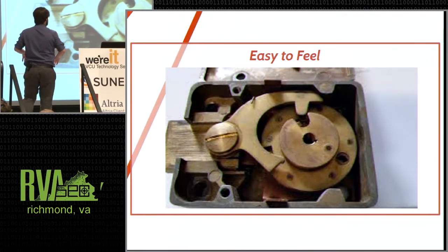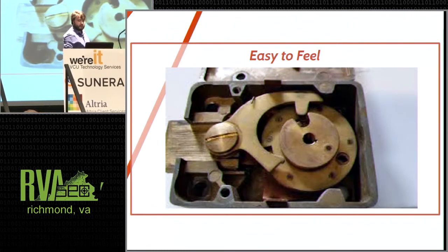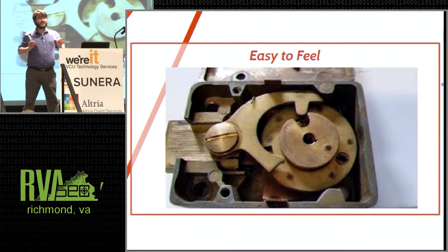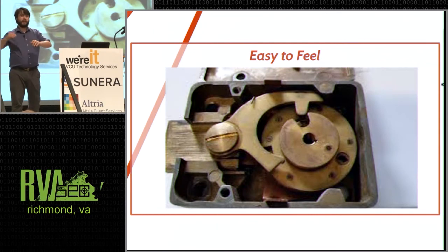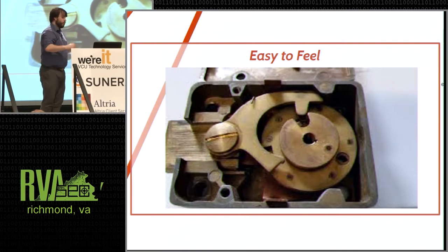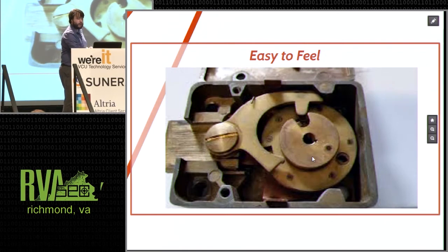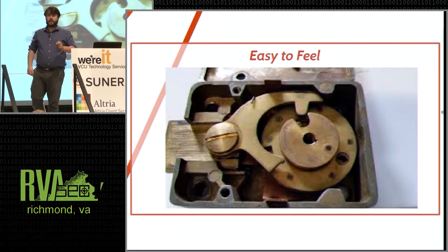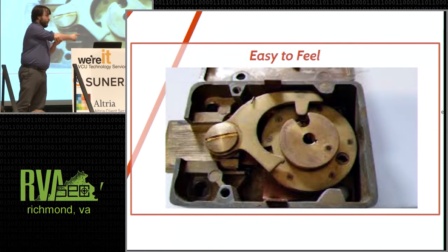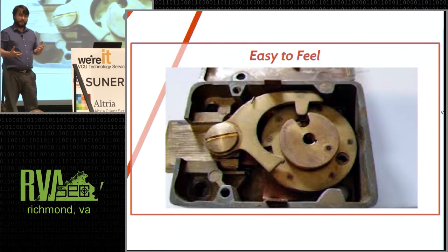Cool. So, they invented what's called the nose. The nose is this little bit right here. Now, the nose is connected to the fence. The fence runs over the top of all of the tumblers in the lock. The nose is riding on this wheel back here, this smaller wheel, and that's called the cam wheel. The cam wheel is actually the one that you're controlling when you're dialing the dial. There's a post running all the way through to it, and that's the one that you're manipulating.